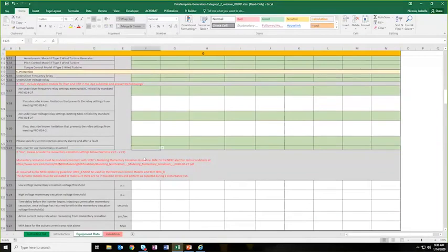The next question for the inverters is whether the inverter uses momentary cessation. So select yes or no. Please be aware momentary cessation means the inverter stops gating during a low voltage or high voltage event, so both active and reactive current are zero. That is momentary cessation. If your inverters still provide reactive current for low voltage, do not select yes. We have seen many people submit inconsistent data here, selecting yes, but then their model shows they still produce reactive current. That is not momentary cessation. Answer no here.